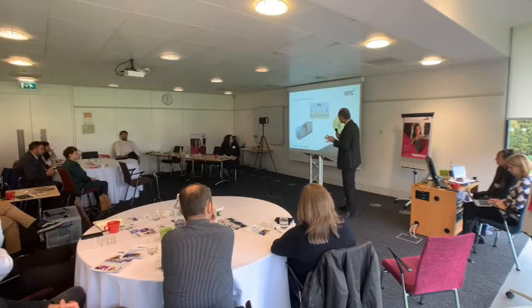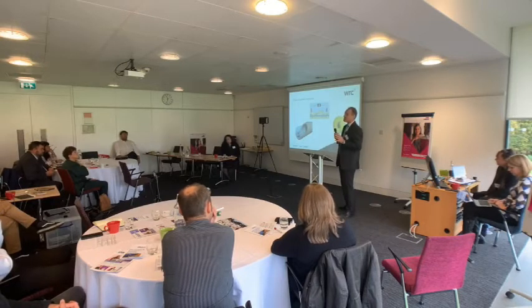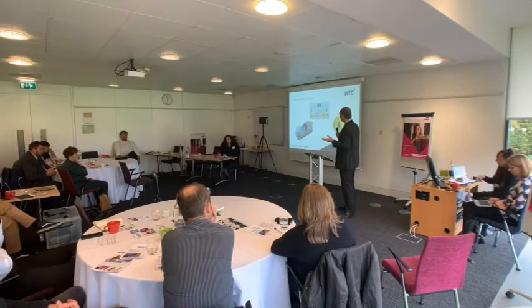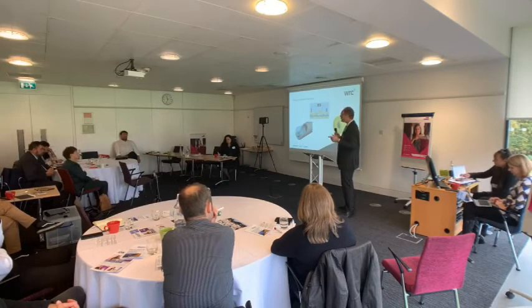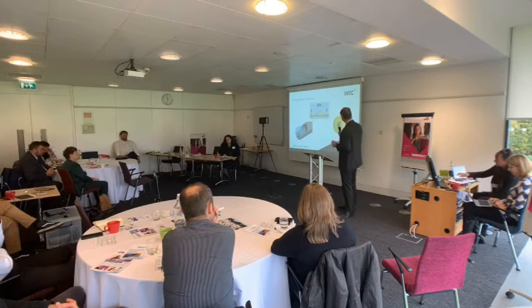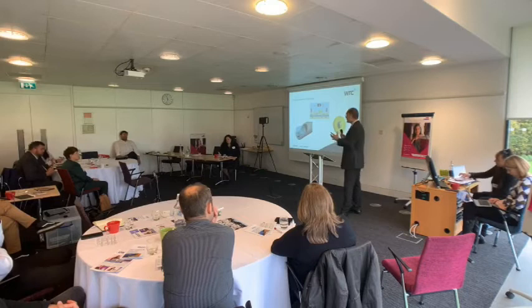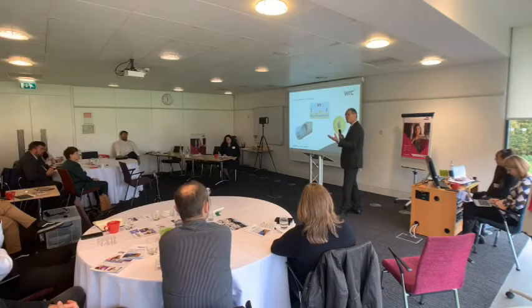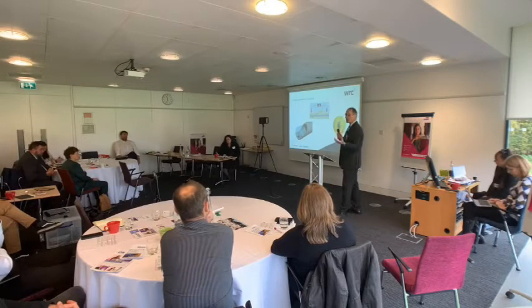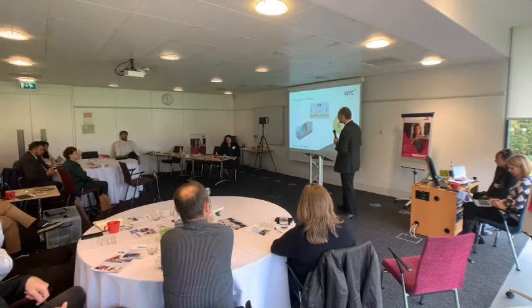That's an in-pipe acoustic leak detection tool. So that's a sensor on a cable moving through the pipe and picking up the sound as it goes. And finally, we'll have a quick look at Smart Ball, which is similar acoustic detection, but it's a free swimming device, so it rolls through the pipeline over long distances, collecting data as it goes. You download the data at the end and analyze it to find the location of leaks.